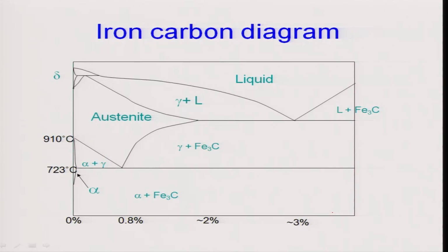As you see here, this is the iron carbon phase diagram, normally people say, but this is not, as today we will come to know. You have the pearlite A1 temperature below which the pearlite transformation happens, that is alpha plus cementite, which I discussed a lot. Then you have austenite or gamma, then cementite on this side. These are the carbon concentrations: 0.8, about 2.01 percent, and this is about 3 percent carbon.